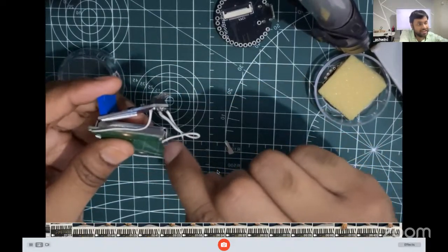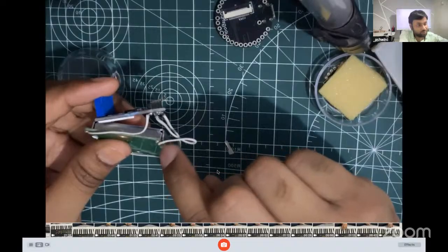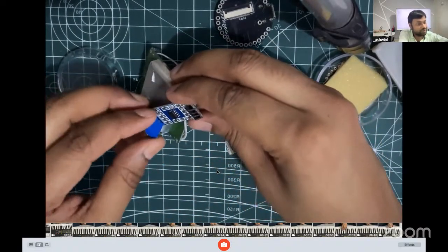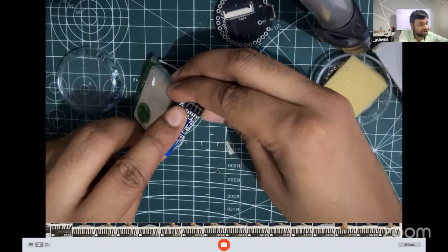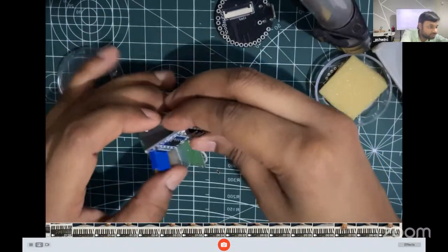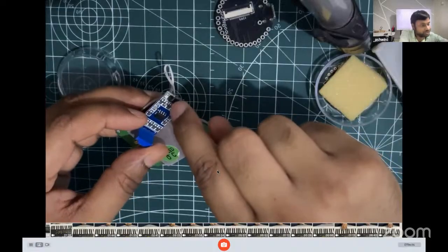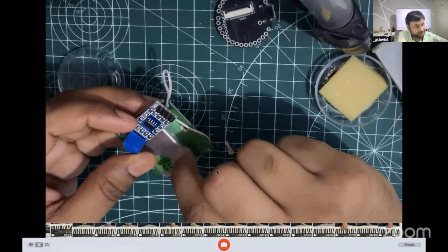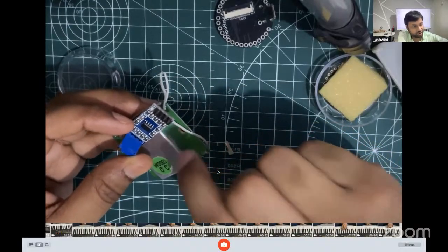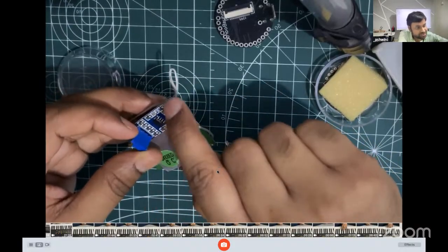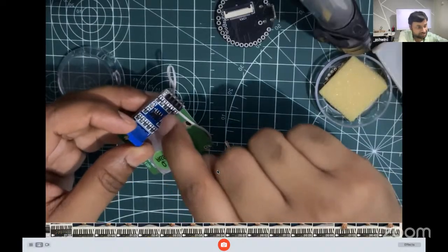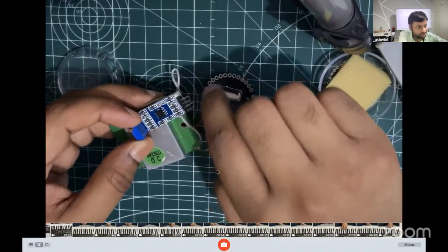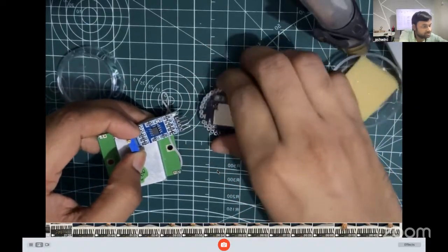We have to connect the IF pin, the output pin of the radar, to the input pin of the amplifier module. Then on the amplifier module, you will see the VCC, ground, input and output pins. The input pin is already connected to the radar, VCC is already connected to the radar 5-volt, and ground is already connected to the ground pin. Now the VCC pin of this module connects to the 5-volt pin of the Indus board, that is the V in pin.